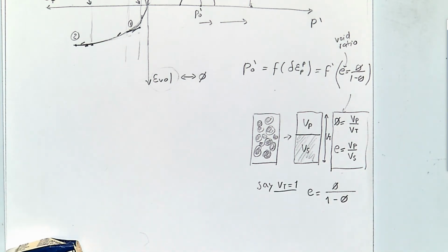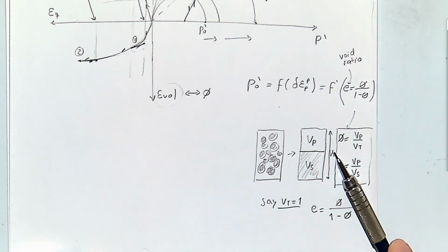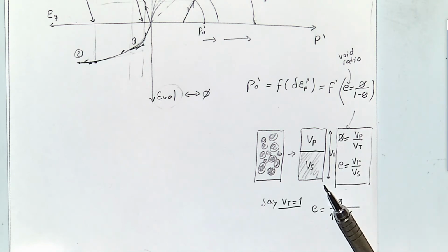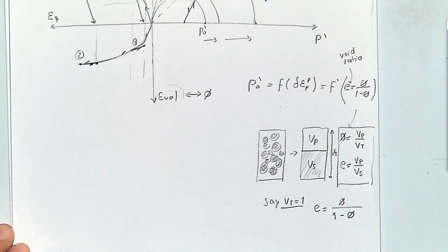So it's just another way of telling what porosity is, but with emphasis on the pore volume with respect to the volume of the solid. For example, if you had a void ratio equal to 1, that would mean that there is as much space distributed in pores as it is in the solids. And that will be a porosity of how much? 50%, right? You raised your hand, Stephanie? Yeah, I think I'm thinking about that a little. Okay.